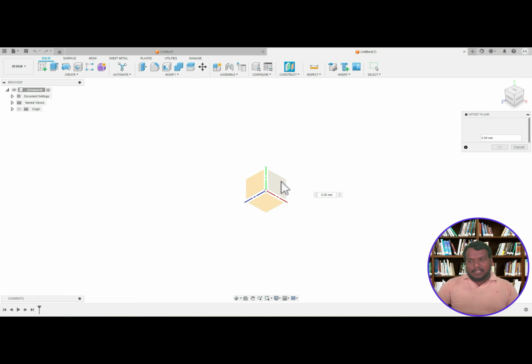So I select the surface, which means one plane was selected. Then the distance. The extent type is distance or To Object. We know that To Object means the next object, where we don't have a distance between the two objects, so for that you use To Object. In case you know the specific distance, we use that to create the plane.